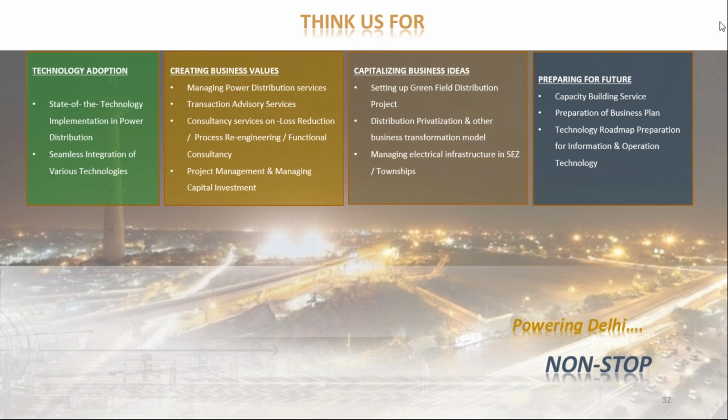Okay. So in automatic demand response, we initially selected around 250 consumers, each having a demand of more than 100 kilowatt. We segregated their load into essential and non-essential load and had a controller in their premises, and we installed the smart meter which was reading the consumption pattern of that consumer, and from a centralized location, we could control their demand.